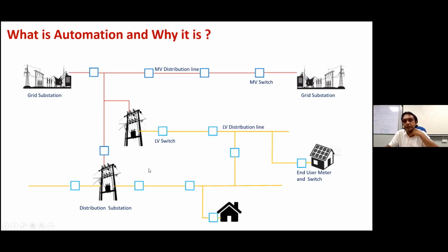Then what will happen? We call the call center, and then the call center informs the breakdown. When they reach this place after half an hour or 1 hour, they manually open this switch as I showed. Then after that they open this T switch and reconnect this switch, and supply is fed to this home through this one.